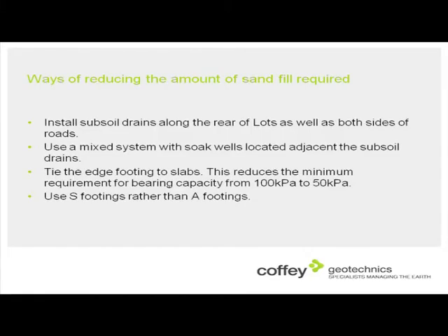A very simple expedient of tying the edge footing to the slab means we can allow the groundwater to be much closer to the footing, and we could just use Class S footings rather than A, and we'd halve the amount of sand we need over clay sites.